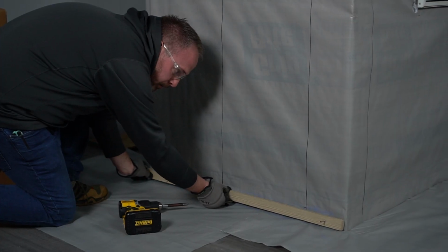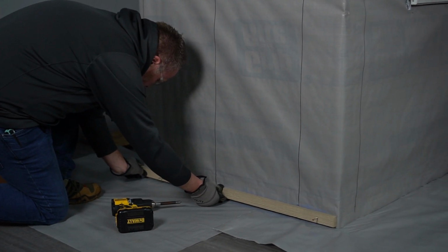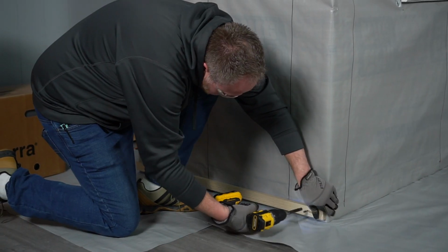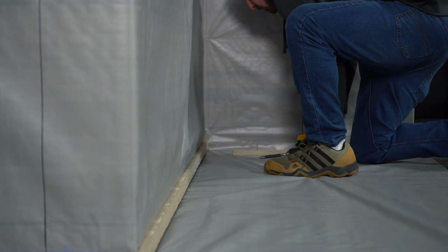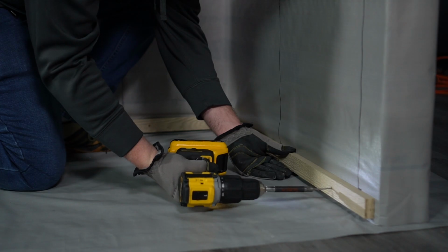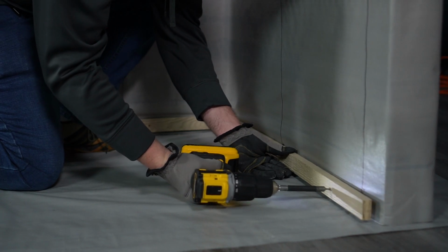Note, it is helpful to continue marking level lines at 2-foot intervals. This allows visual confirmation courses are remaining level. Ensure the board is level and fastened sufficiently to hold panels as the initial course is completed. Once the initial course is installed, remove the leveling board.